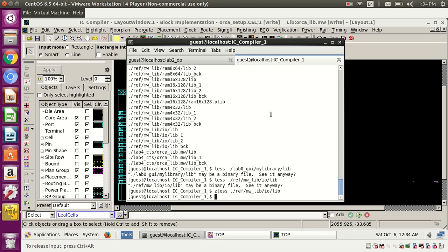That means some data path is going to some flops. So it calculates which data paths will be stable for 10 or 15 clock cycles, and which flops they go to. For all these flops it will add a common cell.